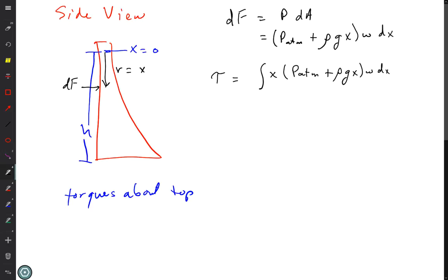So there's my torque. What direction will this torque be? Given my picture, what direction will the torque be? Okay, R cross F is coming out. That's correct. Because I had to put my index finger in the direction of R, which was down, middle finger in the direction of the force, which was to your right. Your thumb comes out of the screen toward you. So it's a vector, but here I'm just doing the scalar calculation. I use the right-hand rule to get the direction.